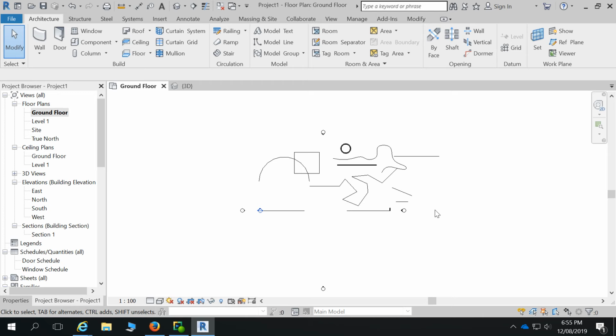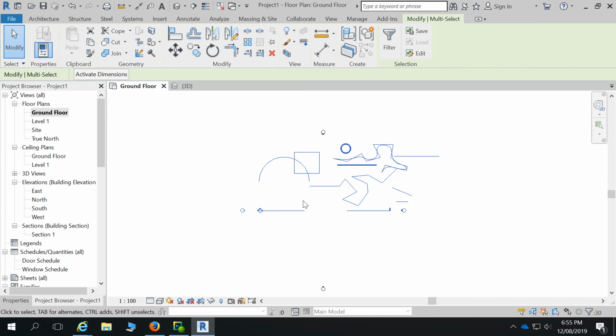So when we use that window crossing, it might not be perfect. We might say, well, it's grabbed everything, but I want a couple of things less. We can easily take those things out, rather than have to go through and go, well, I only want this one, and oh no, I've just hit something I don't want, do it again. It's just a little shift, hold the minus and deselect something, maybe like that, okay?